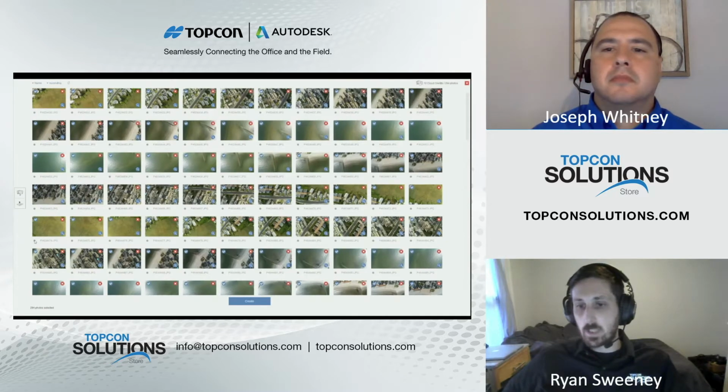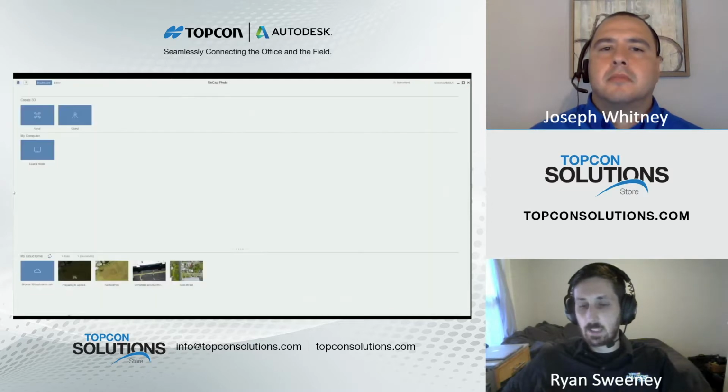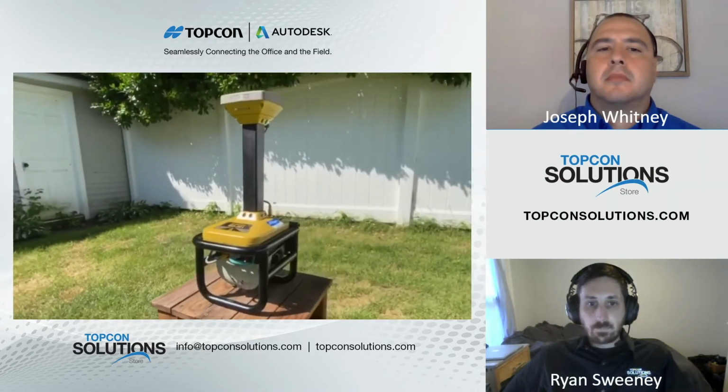And we're going to do that through all those photos on each GCP. And from here, we're going to hit create and start the upload process of those photos into Recap Photo so we can get our good, accurate 3D data and orthometric photo to be able to bring in and use in Recap later on.